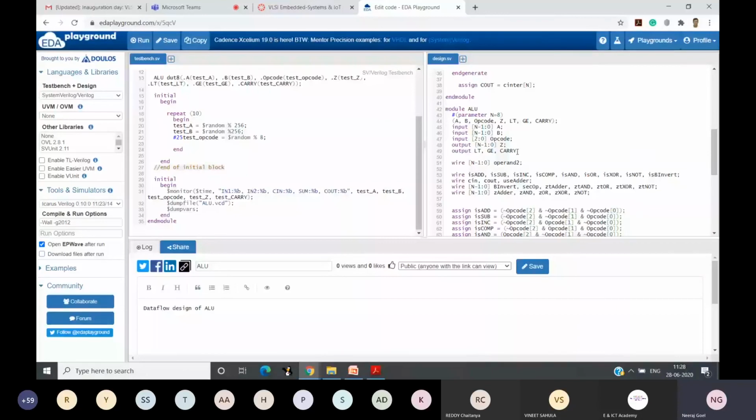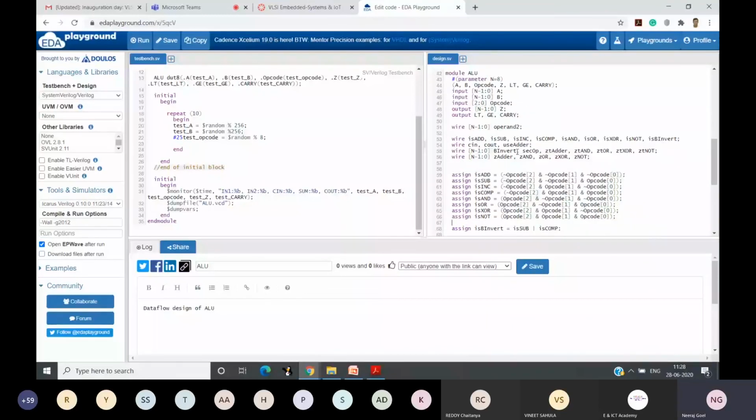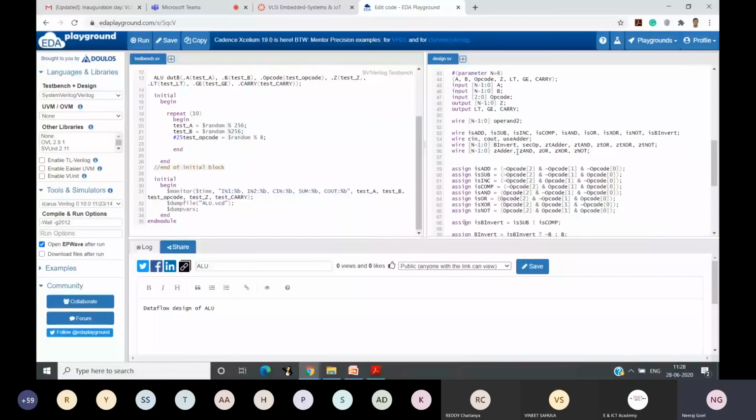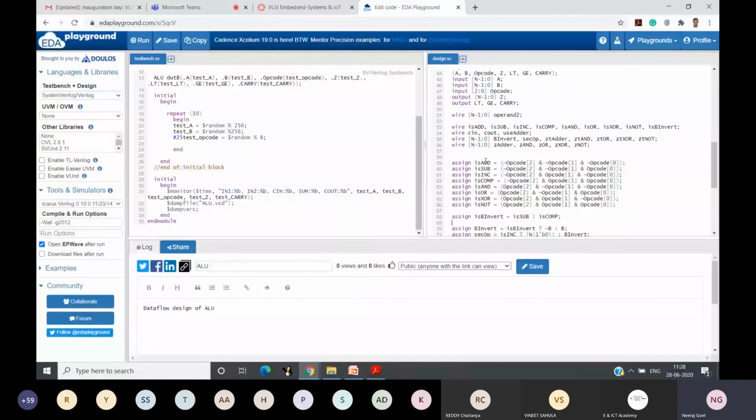So the first thing we do is the decoding part. In decoding, we try to identify whether it is add or subtract. If you see this particular logic, this is essentially a decoder, where the inputs are 3, and based on the 3 inputs, we are generating 8 outputs. Now we have written the standard decoder manually. In this manual writing, we have 000, then 001, 010. Similarly, all the conditions have been enumerated. They are a simple decoder implementation in our data.